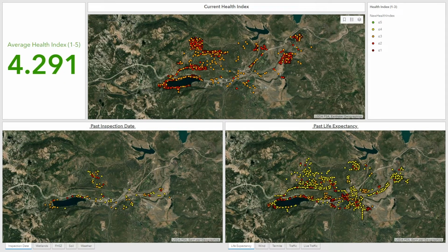So when I develop my capital refurbishment replacement programs, these are the poles that I'm going to be saying we need to change out, and it's purely based upon age, because that's as much information as I had at that point in time. What Tyler's just done above, he's done another set of analysis and determined that there are huge clusters of poles that have come back and their assessment of their health is low.